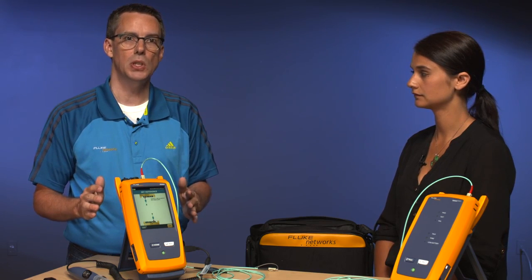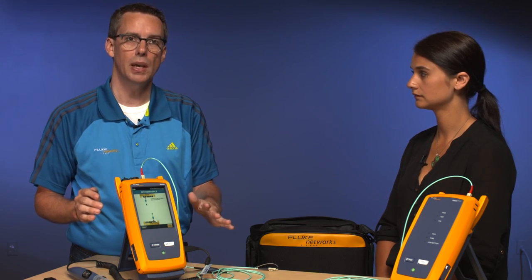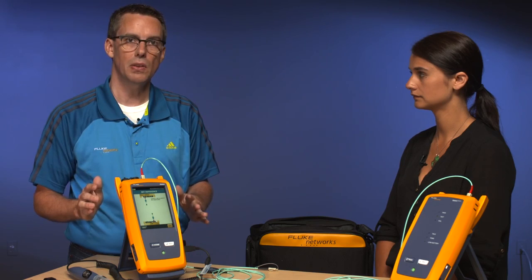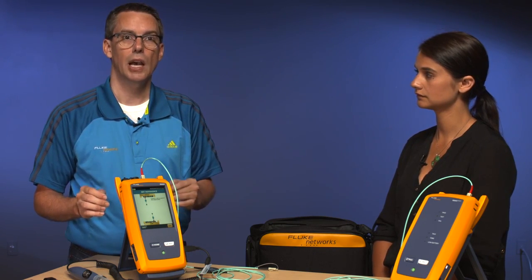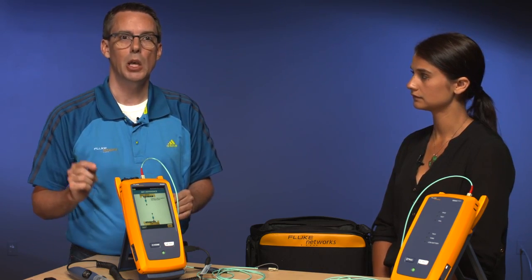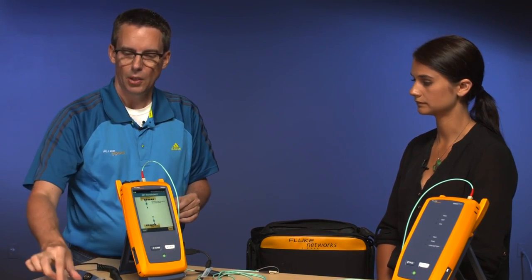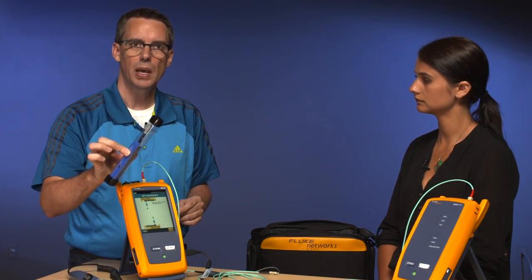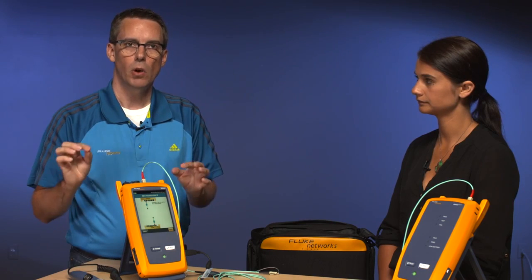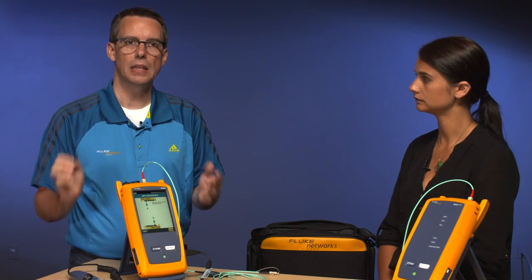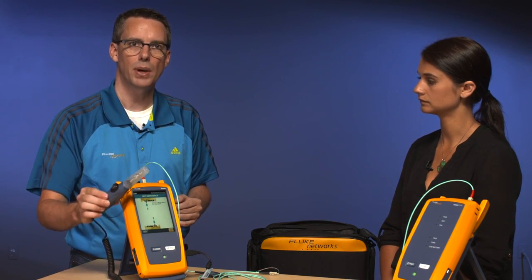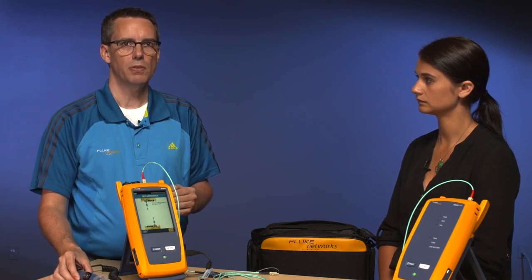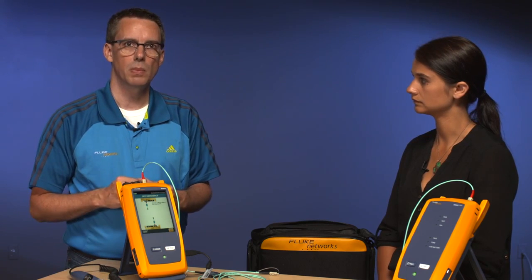That's very important to do because even though they're brand new out of the bag, that's no guarantee that they're clean. In fact, we did find a couple of them were a little bit dirty on the end faces, and we cleaned them, and more importantly, we inspected them again. You can clean them using these one-click pens, but the false assumption there is that once I clean it, it's cleaned. You don't know it's clean until you've inspected it. So without a camera, you're going to have a pretty rough time doing your fiber optic measurements.